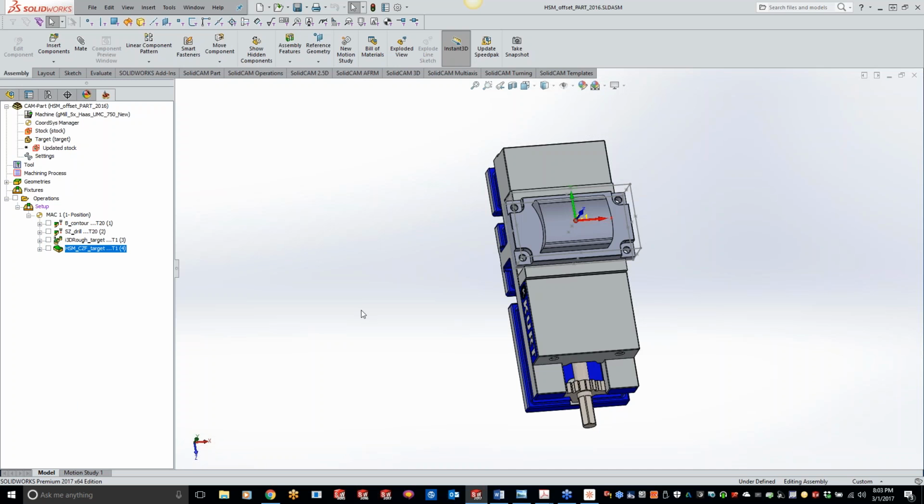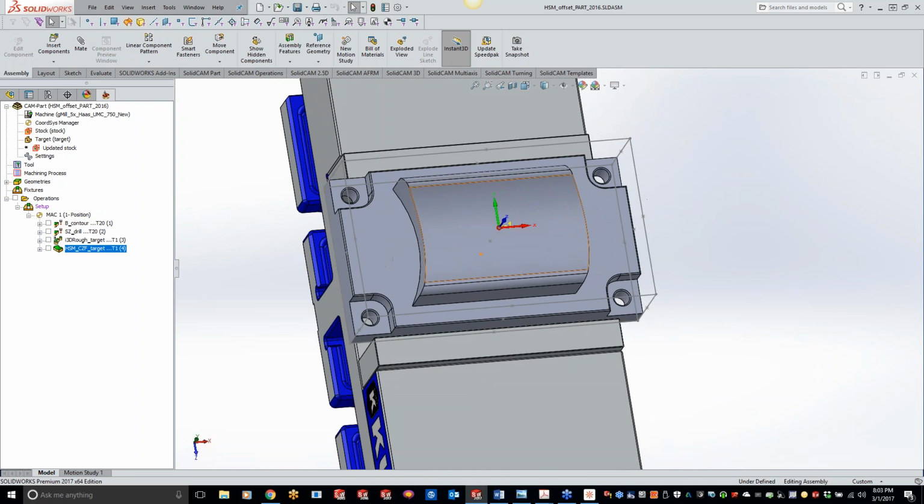Okay, so first what we're going to talk about is the offset cutting. Basically, offset cutting is pretty similar to how the morphed cutting works. Now, you guys remember last week we have our part right here, and we did a morphed machining, and this was actually curved. Basically, the opposite way is this one. And what the morph did is we just picked the guide curve on the one side and the other side, and the tool path corrected itself and then followed the form around.